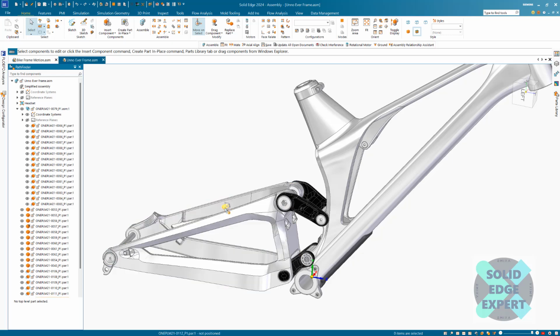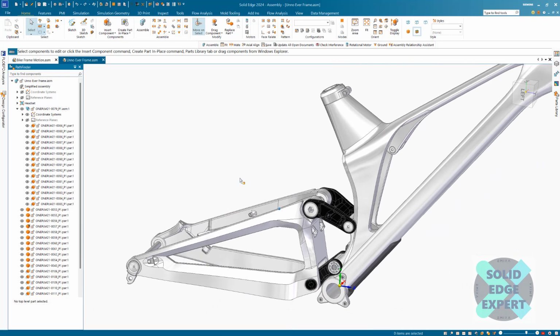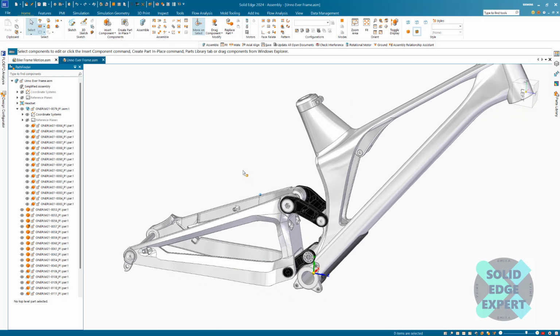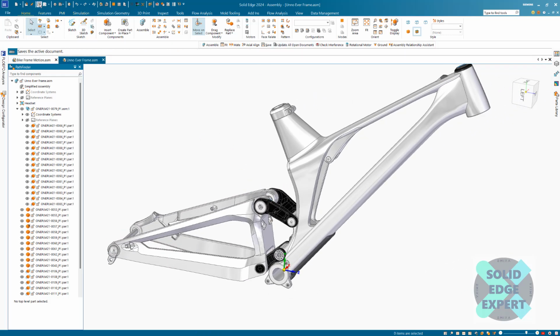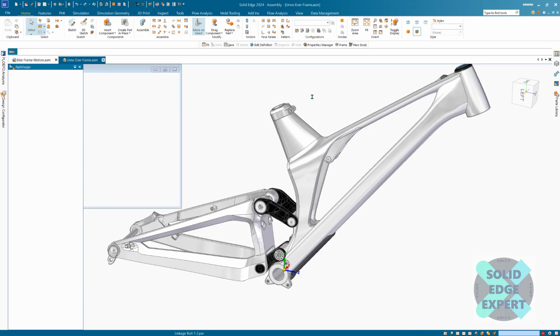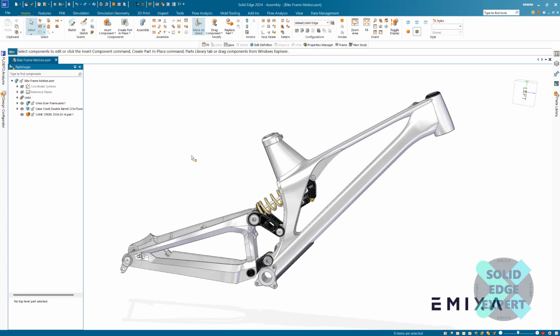Also make sure that little bits like this are physically constrained in properly. If you do a pattern, they won't update, so I always like to either clone or constrain those in as well. So let's save that and go back to the top level. We've also got similar on the rear shock on there as well. So that's got similar, that adjusts within its degree of freedom. But we want those to adjust in their degree of freedom at this level as well.